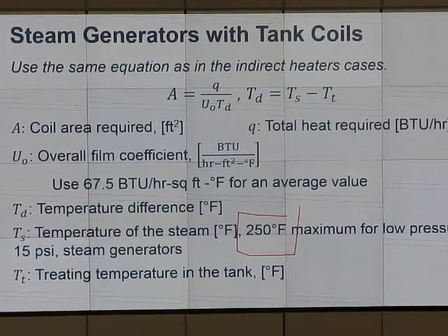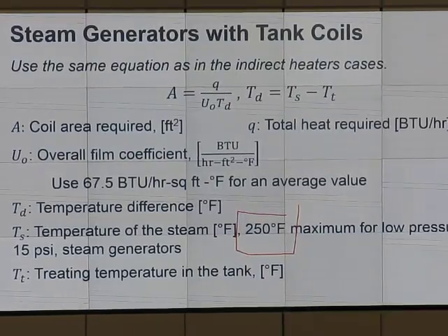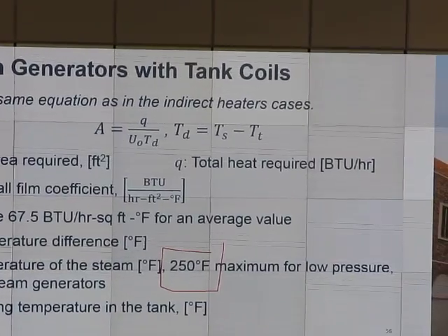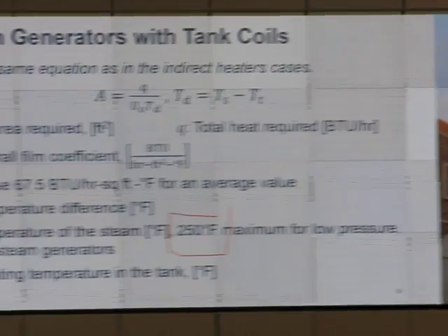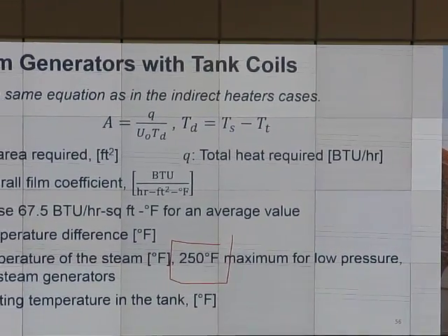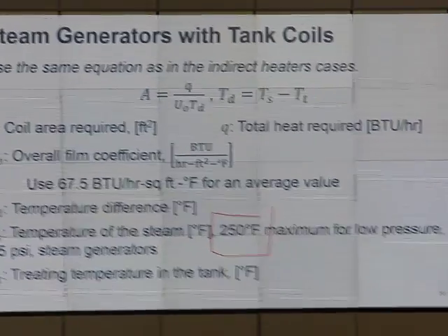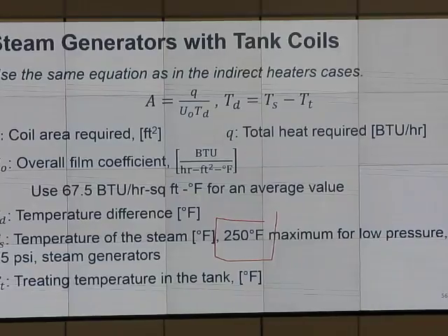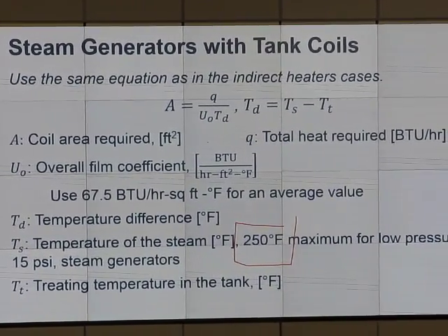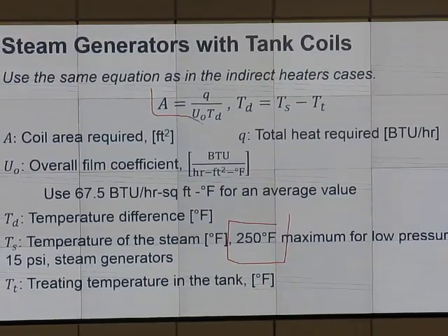So if we do steam, we can do hotter. Okay? So this is for tight emulsion that require more heat, more retention time, and corrosive. If it is not corrosive, just use heater treater. Because it's indirect heating, the name suggests, right? It's indirect. It's not as efficient as direct heating. Okay? And you do it the same way that you did earlier.